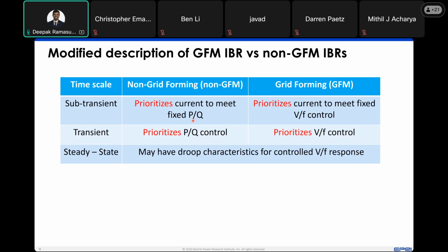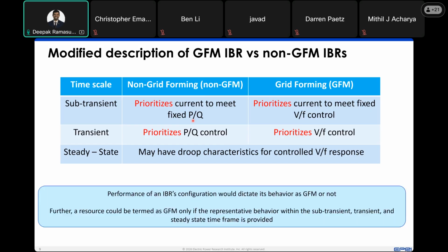which goes back to our PQ bus that we had spoken about, which goes back to the aspect that even though the AC voltage of the inverter is being developed in order to increase the current that is being injected, it is doing so in order to keep P and Q constant. That part is what results in a reduced stability profile that we have in the network.